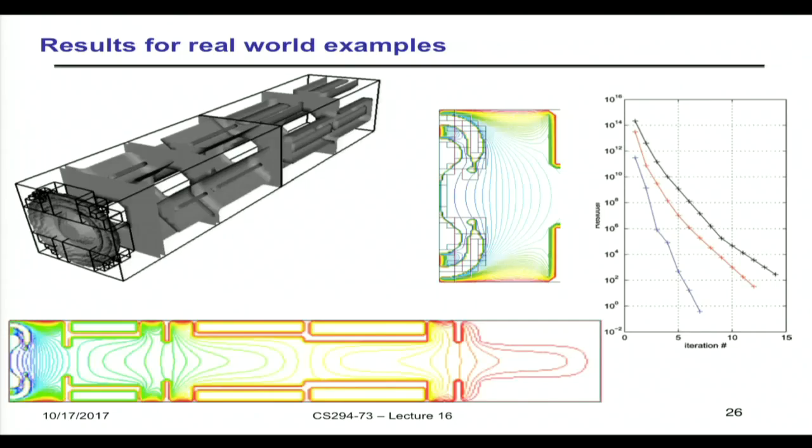So this is something from our group. This is a 3D combustor basically in this kind of a channel. Or is this the plasma chute? I can't remember which one this is. I think it might be the combustor. But basically these are adaptive mesh boxes, and each of these boxes is a, let's say, 16 cubed structured grid domain. And so you're solving all of these nested boxes on this large domain, this entire tube.